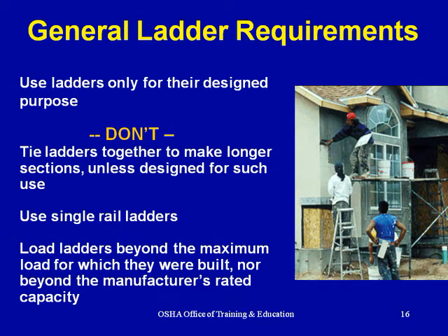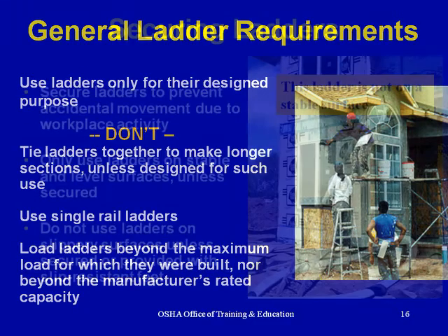General ladder requirements. Use ladders only for their designed purpose. Don't tie ladders together to make longer sections unless designed for such use. Use single rail ladders. Don't load ladders beyond the maximum load for which they were built, nor beyond the manufacturer's rated capacity.